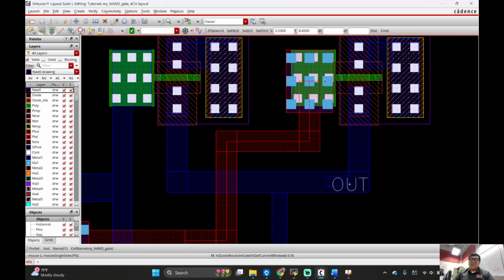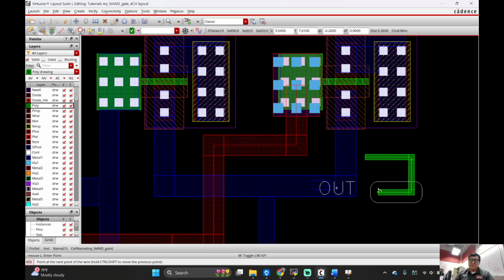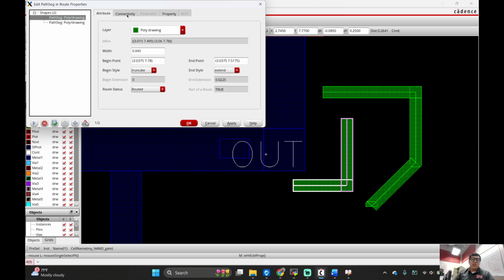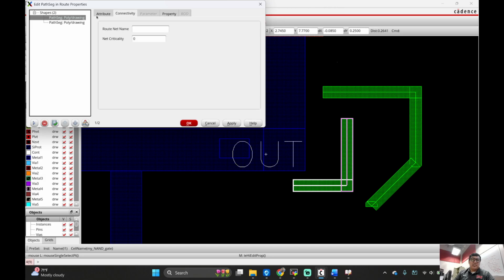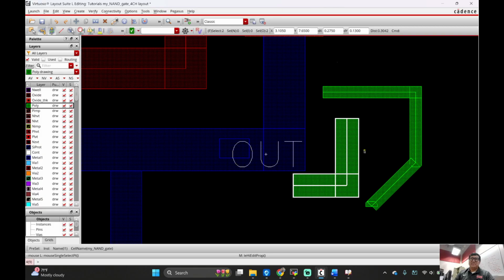But anyways, here I went to level 2, metal 2, right? And then I used the P tool. If I press P right here, I can, and just like that, you see? Actually, I don't like that. Boom. If I click and double click, it establishes a line, okay? If I want to make it thick, I just press Q, go to width. Actually, this is for a poly, but if I wanted to make it 9, I can. Sounds cool? Any questions about that?